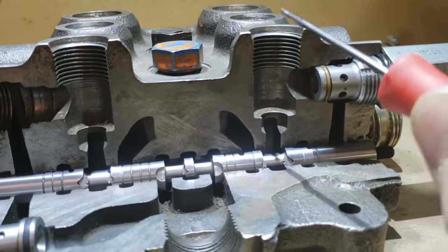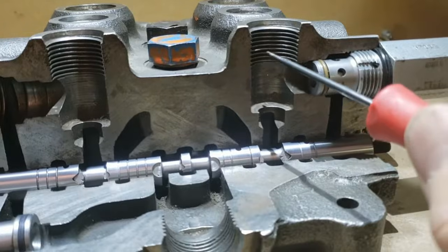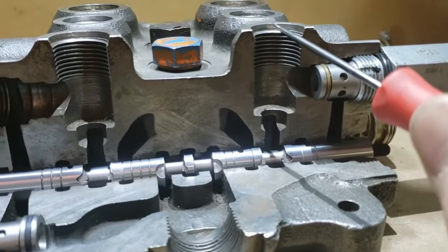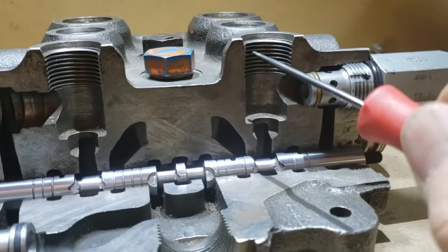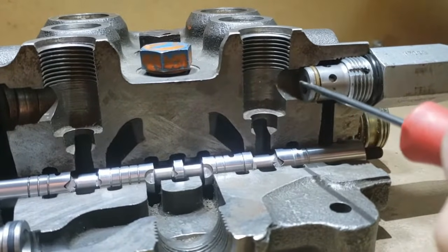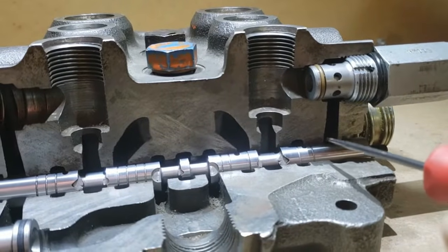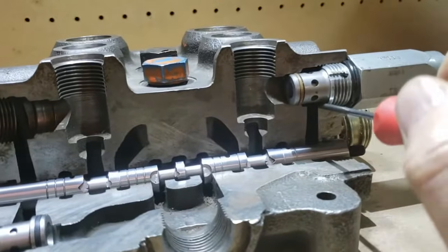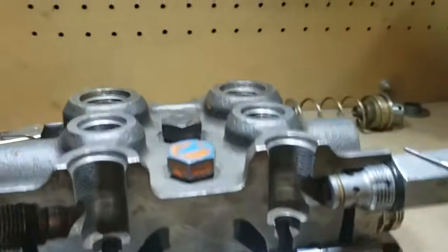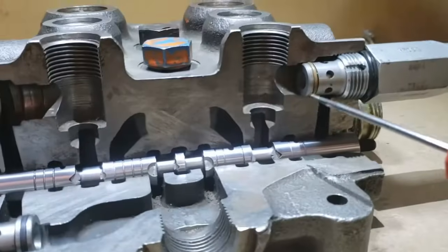So if something forces that cylinder to want to retract on the machine, you run into something when you're driving it, or a big rock rolls off the pile and lands in the bucket, and it makes a big pressure spike here, that pressure can blow open this relief valve, blow out these radial holes, which dump into this passage, which go back through the casting and back to tank. They bypass all the functions around to here. So that's a port relief.